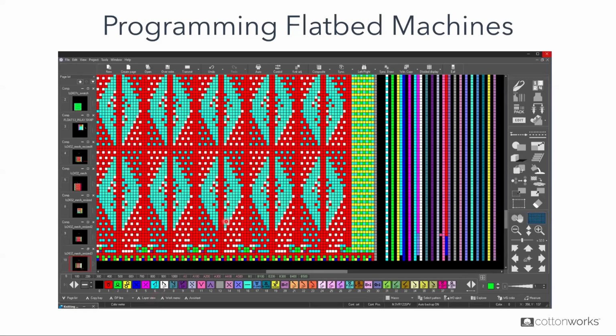The control columns, we have 20 on the right and 20 on the left that you can't see on this screen. But this is where we control which yarn feeders are used, how fast the machine is running, what direction the carriage is running in. We control all of the elements of the program here. Again, we have the same or similar processing tools because this program also needs to be turned into knit language in order to transfer it to our machines.